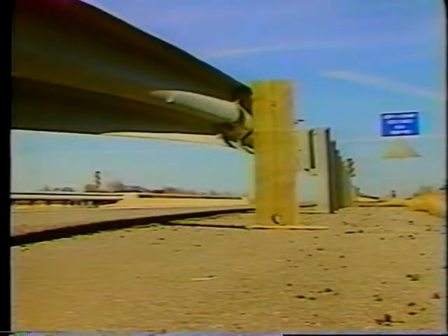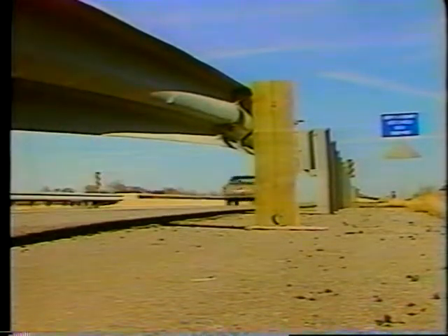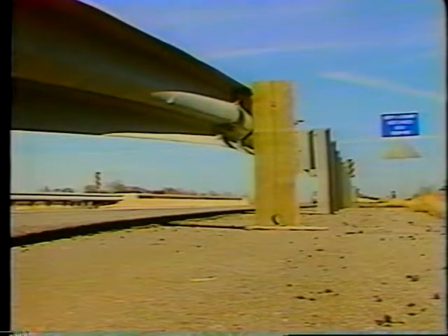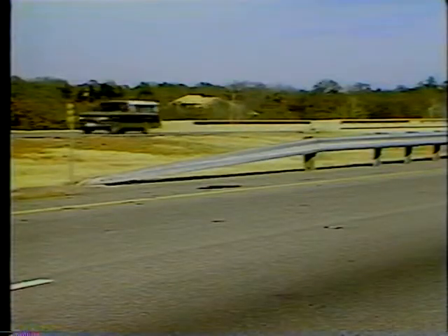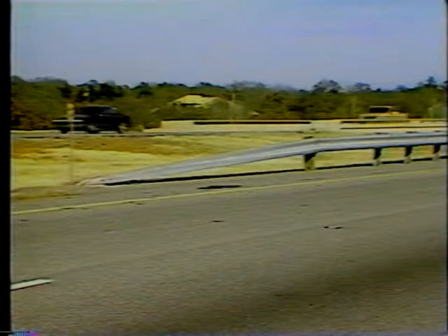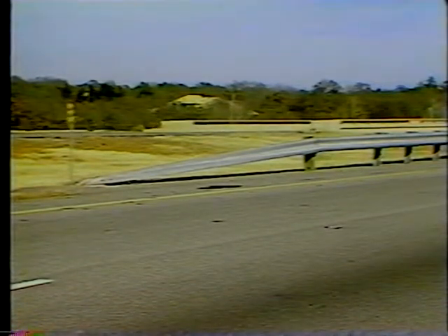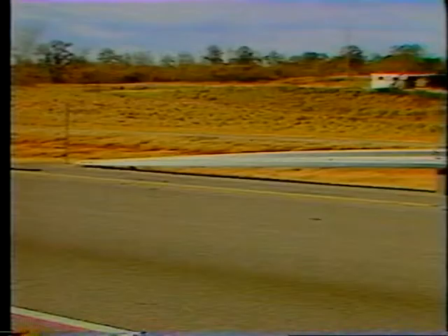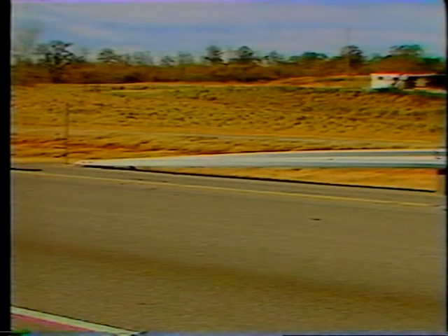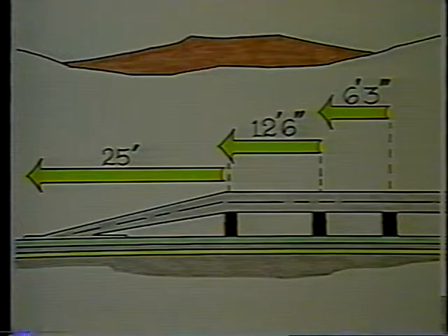The impacting vehicle then either continues on to shear off weakened posts or until it decelerates to a stop in a runout area behind the rail end treatment. With this system, spacing of the first 3 posts is important. The twist and turn down occurs in the end 25-foot section. No post should be set within the twisted section. The second and third posts are spaced 12.5 feet apart, with remaining posts set at 6-foot 3-inch intervals.